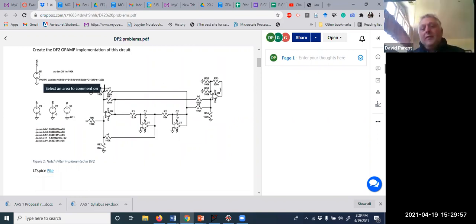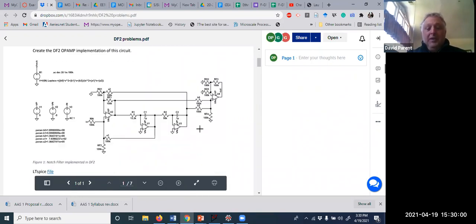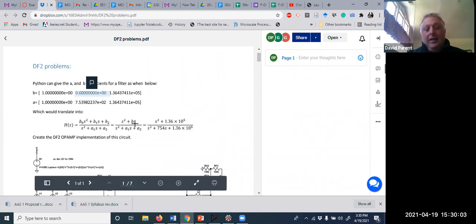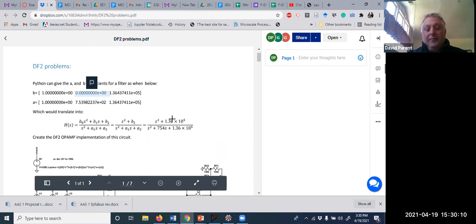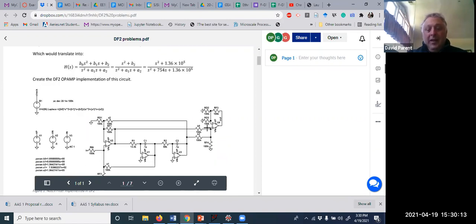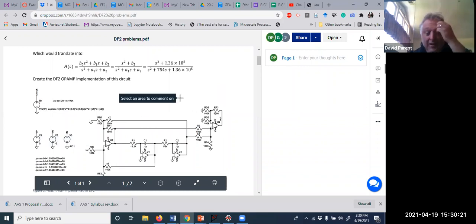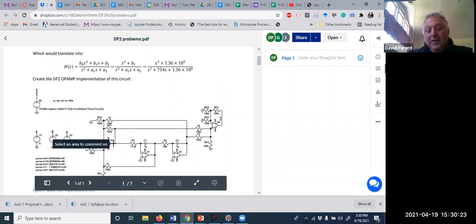Now, the B summer. The B summer is adding in parallel the orders of S in the numerator. The constants are B, and that's why I call it the B summer, although you could also say, I always draw this before that, so that would be AB. Coming out of the output of the summer is non-inverting, so keep it non-inverting. Then I have two stages, and I keep it non-inverting. And then I balance it.